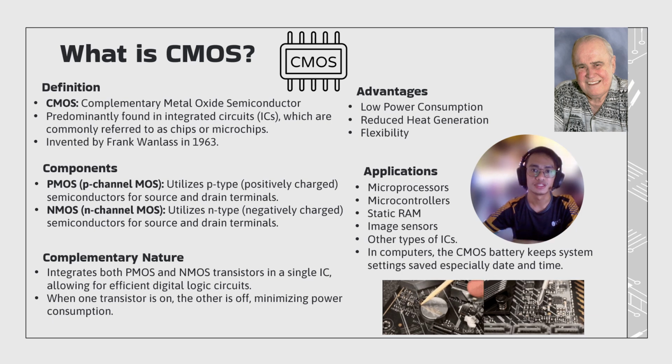And in computing terminology, you might also hear about the CMOS battery or CMOS setup. This refers to a small battery on a computer's motherboard that powers the CMOS memory, which stores system settings and BIOS configuration. So basically, if your computer's date and time keep resetting, it is often due to a dead CMOS battery.